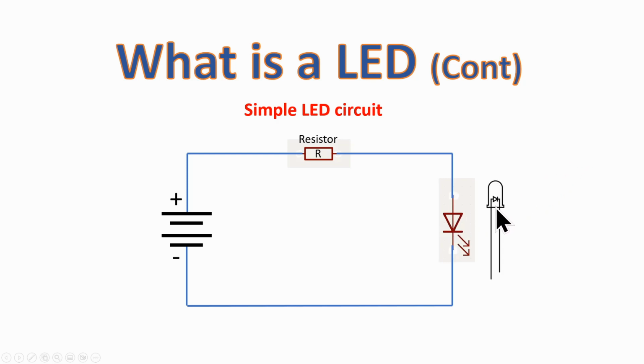So the LED itself looks something like this, the ones we're going to use. I think the ones in the kit, if you purchase our kit to do these experiments, are 5 millimeters. This is a little dome. I think we give you red, green, and clear, or white. The long lead on these LEDs is always the positive side, which would be this side, and the shorter is the negative. This is called the anode, and this is called the cathode, which would be on this side.